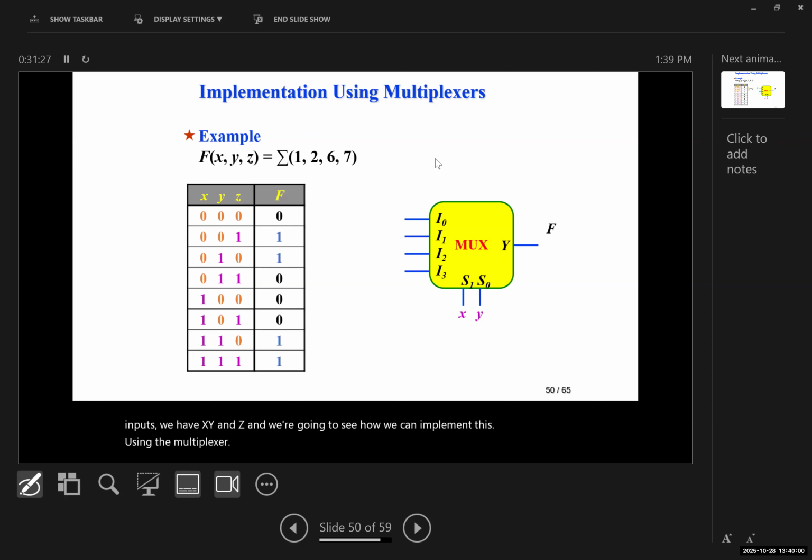By the way, previously at the beginning of the combinational logic circuits, we learned that we can implement these using logic gates and logic circuits. You remember we did a bunch of problems and solved it. But instead of doing it using a lot of logic circuits, we can do it with a single multiplexer. It's going to be much easier. But I want you to think on how we can do that and how I could actually connect these to implement it using the multiplexer.